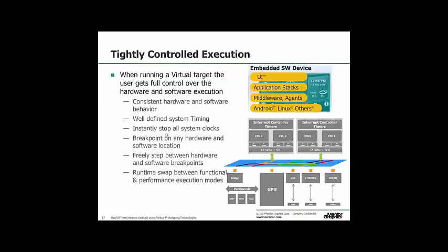Quite often it's important to be able to connect real-world I/O with one of these virtual prototypes in order to get some kind of real stimulus into the platform and also to get some results out. So we normally have some type of I/O model as part of a platform, whether it's an Ethernet device, USB, displays, keyboards, etc. These actually behave exactly the same as real hardware.